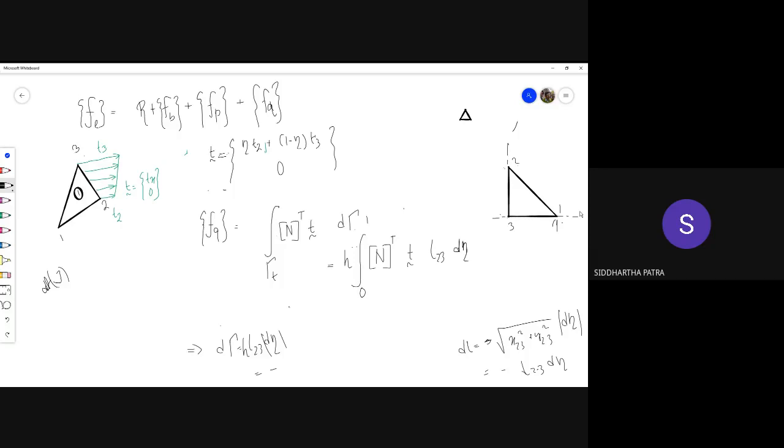And the value of the Jacobian or the sign of the Jacobian becomes an indication of how the solution is progressing for the software. Now you can either consider the determinant of Jacobian to be the volume of the element or the negative of the volume. Okay, that means if you take clockwise, the determinant of Jacobian would be negative of the volume. Okay, that's all I'm saying. But if that is the convention you are working with, okay, that is fine.